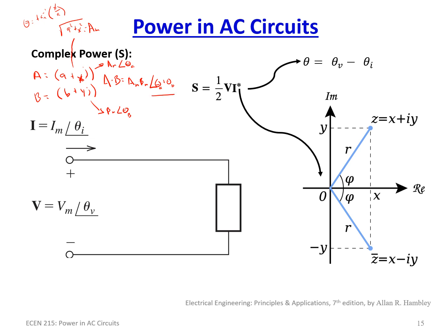So this is where the problem lies. We don't want to add the angles, as what we were learning earlier in looking at the trigonometric identities for power. When we do P is equal to V(t) times I(t), which is what we're wanting to do, this is the real physics. This ends up requiring that we have this net phase difference of voltage minus the current. So that's what we need. But if we do simple multiplication of A or B, or in this case, V and I, we end up with this positive here. Well, we can't have that.